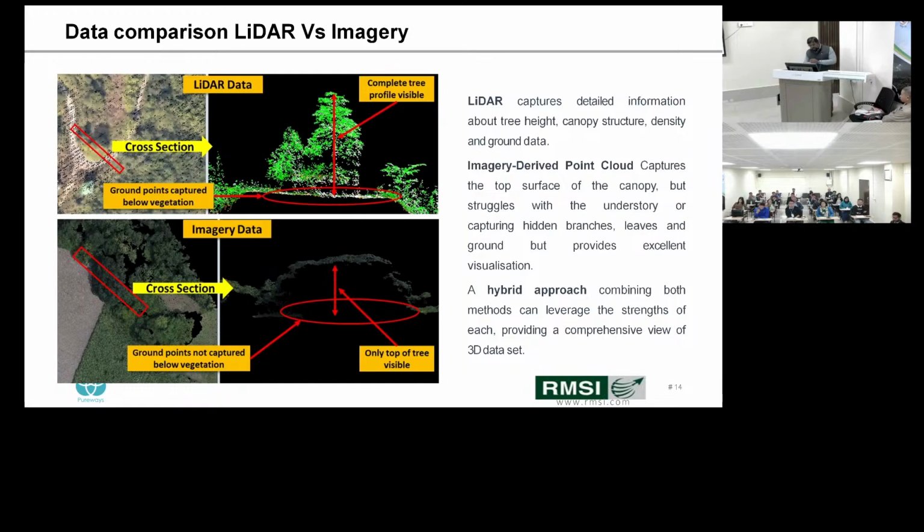So tell me, for the northeast region, which technology is suitable, photogrammetry or LiDAR? Why? Because the entire northeast is covered with a lot of trees. If you go to Rajasthan, photogrammetry can work because most of the areas do not have trees. There, both LiDAR and photogrammetry can give the same accuracy because it is open land.